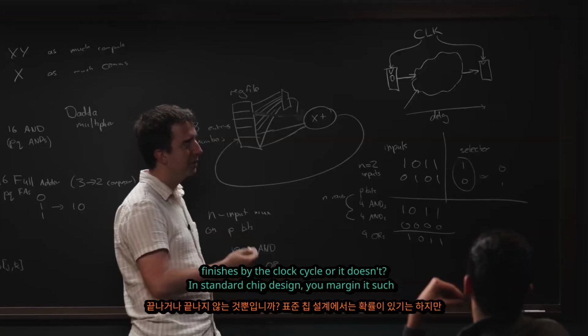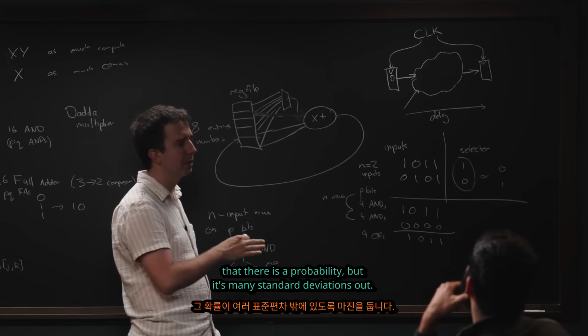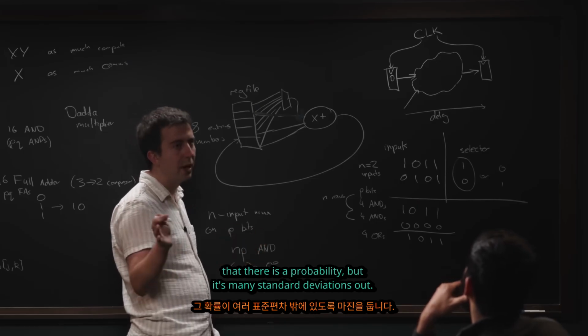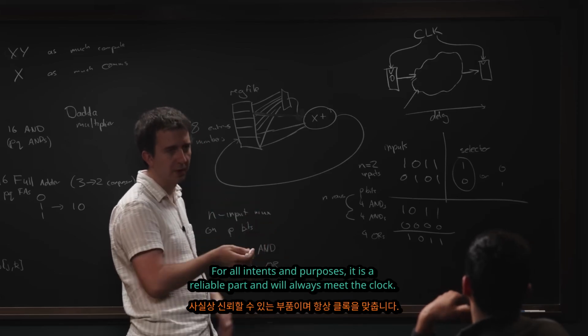Yeah, in standard chip design, you margin it such that, I mean, there is a probability, but it's many standard deviations out, such that for all intents and purposes, it is a reliable part. It will always meet the clock.